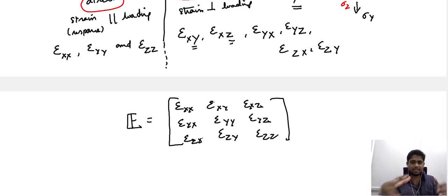Now, what we essentially have achieved is, we have represented the direct and the indirect response that is offered by the material under triaxial loading condition. We are moving away from biaxial. We have started with uniaxial, moved to biaxial, now to triaxial. The triaxial now has helped us present the strain in a comprehensive manner, and depending on the loading condition, we can reduce this comprehensive representation of strain to appropriately fit our desired condition.